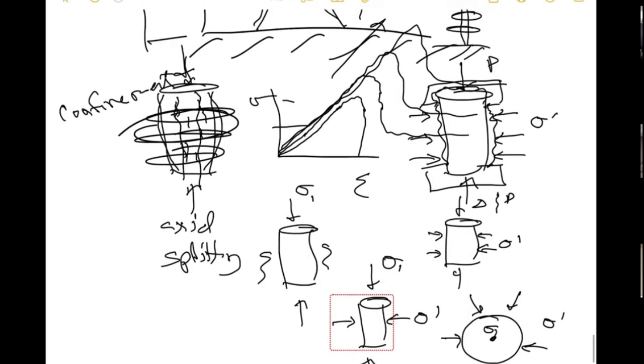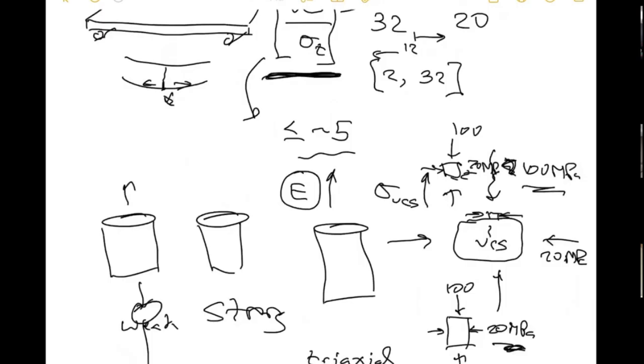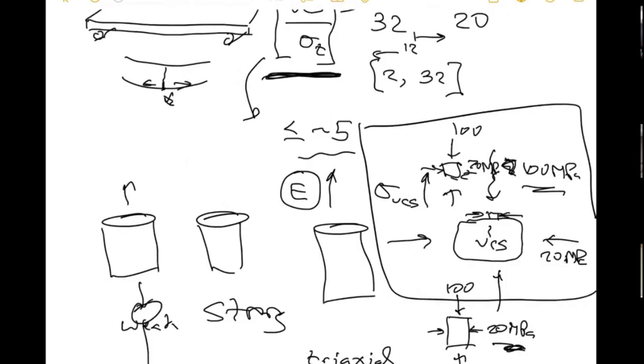And the reason we care is, again, for this reason. This is my excavation. So far away from the excavation, the rock is confined. It's stronger. When you make an excavation, you're changing the confinement and the rock gets weaker. Think about if there was no excavation. The rock's just been sitting there for 1,000,000 years. It's totally able to sustain this amount of stress.